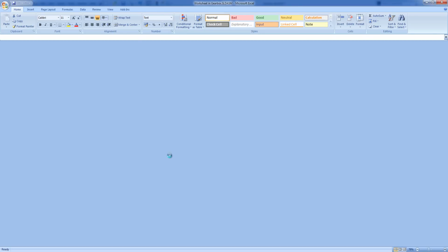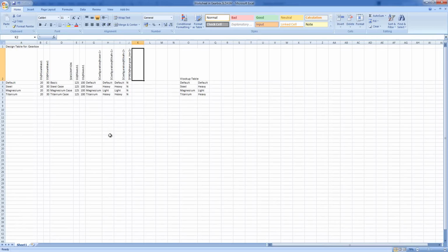Now, in an assembly, you control assembly details. So I've got the distances for the gear mate to make sure my gears hook up, descriptions of my configurations. We've got a sketch which I'm controlling. We've then got the configurations of particular instances of parts. So this is $configuration at case instance 1. We've then got configuration at shaft instance 1 and shaft instance 2.